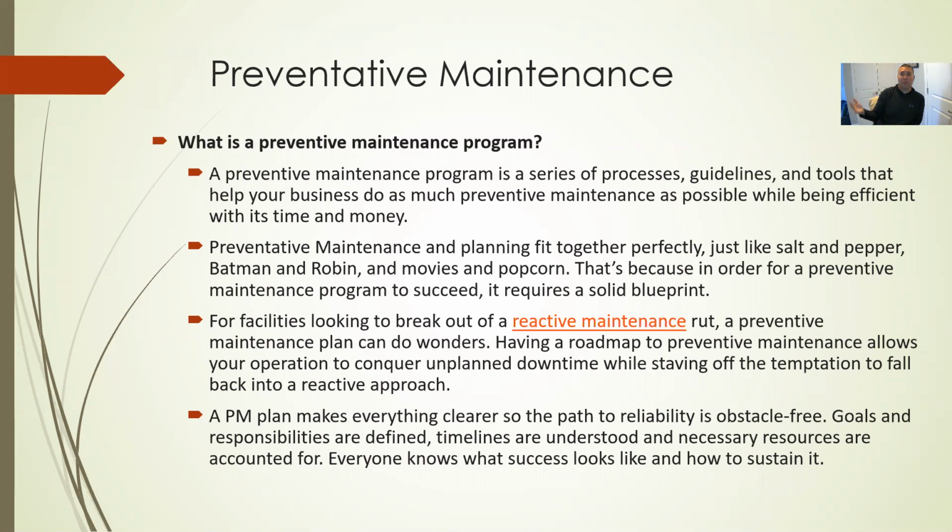If you're not doing preventative maintenance on that, it's not a $5,000 unit, right? I mean, it's a $150,000 unit that's running that school building. So if you're not doing any preventative maintenance on that, changing air filters, right? Whatever else you do to HVAC units, that $150,000 piece of equipment is going to break down a whole lot sooner and not last as long as it should if you're not doing that.